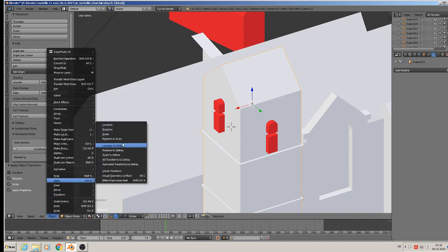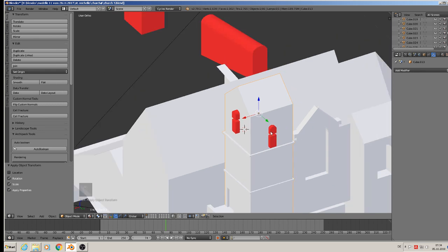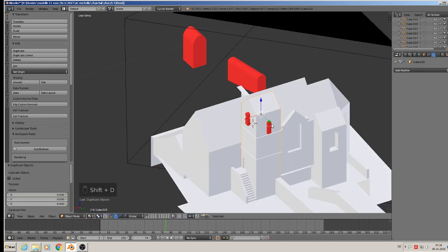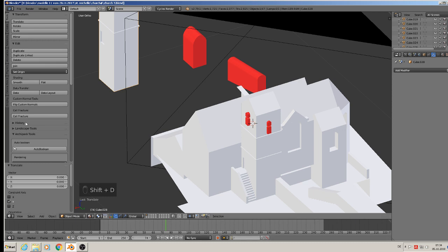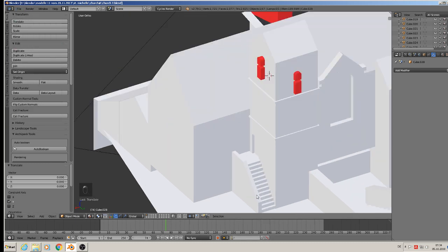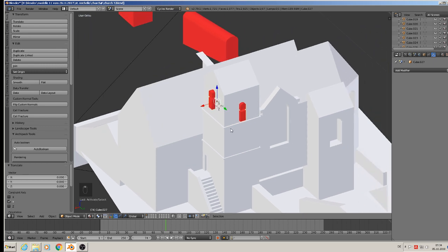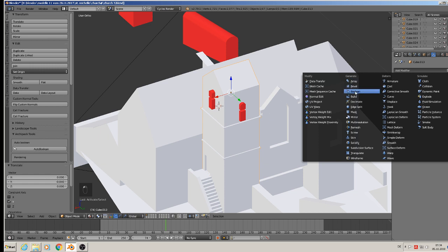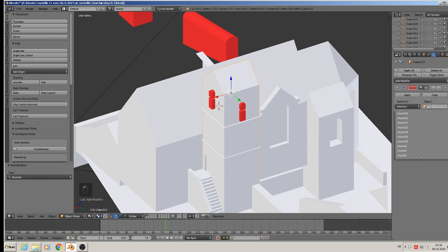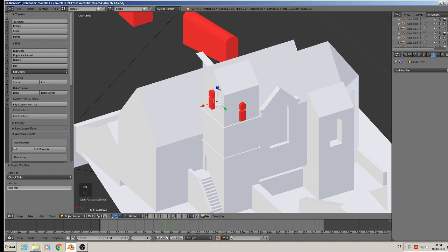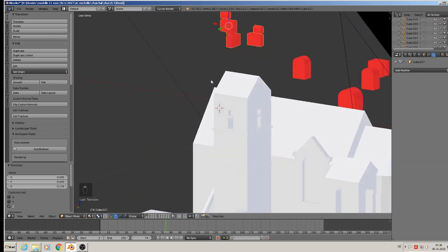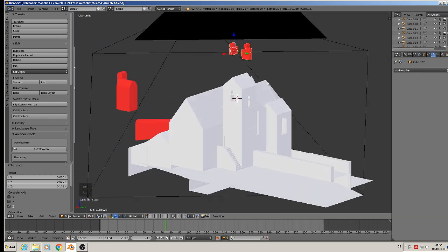Object, apply rotation scale of the tower itself. Then we make a copy of the tower, secure copy, Shift D, place them there. File, save. The name is cube 27, so boolean cube 27 should be the difference. Apply. Wow, we had luck. It functions. Okay, wonderful.